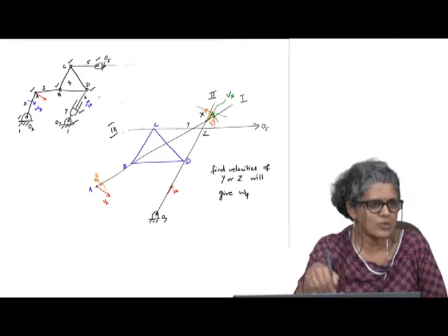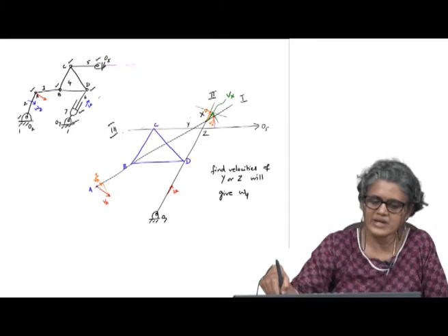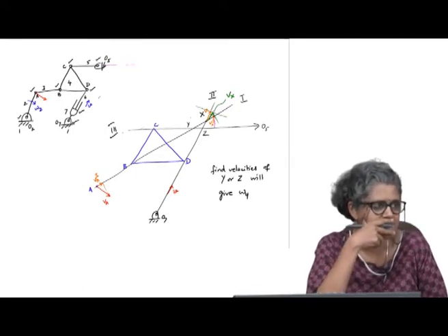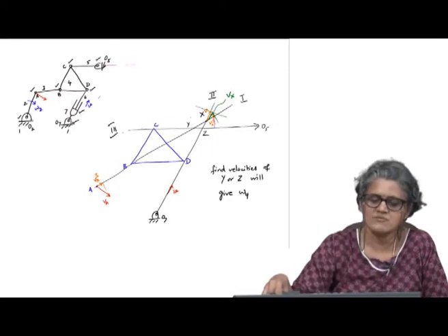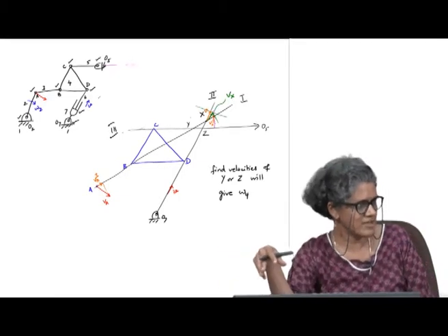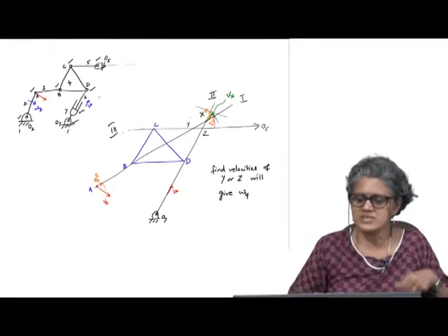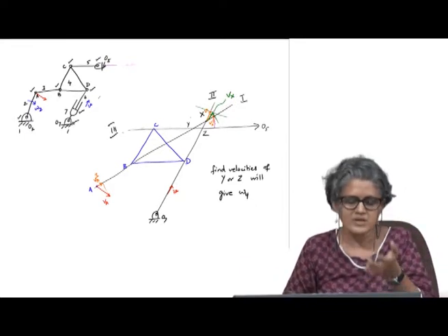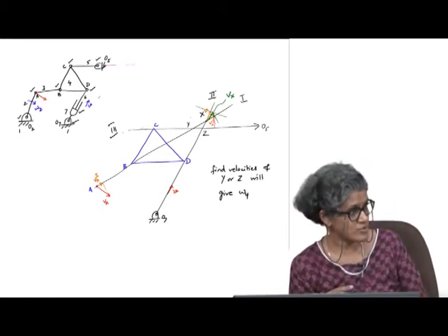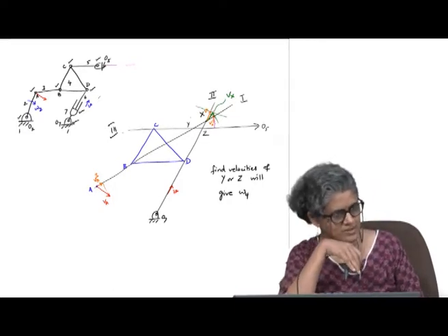So, I can do that in one shot basically if I take C. Here I would find this, and then I would have to find omega 5, because from omega 4 I will find the velocity of C and then calculate omega 5. Okay. So, this is the auxiliary point method. So, for example, we have not really analyzed these kinds of complex mechanisms by any of the regular methods.